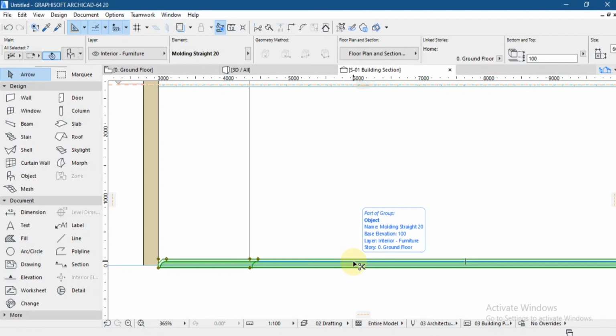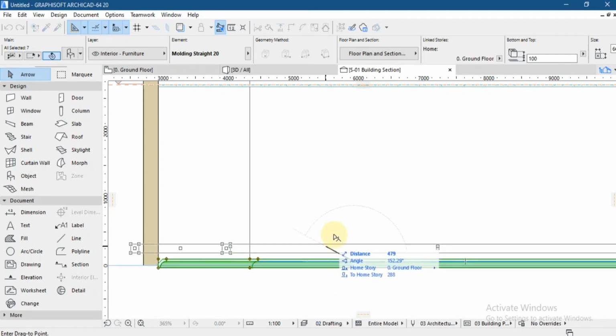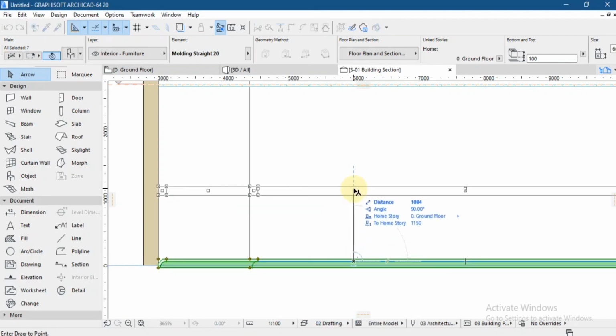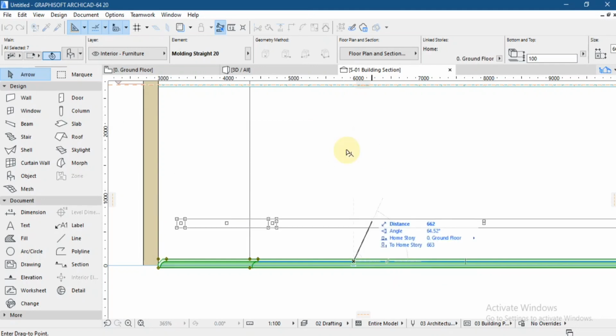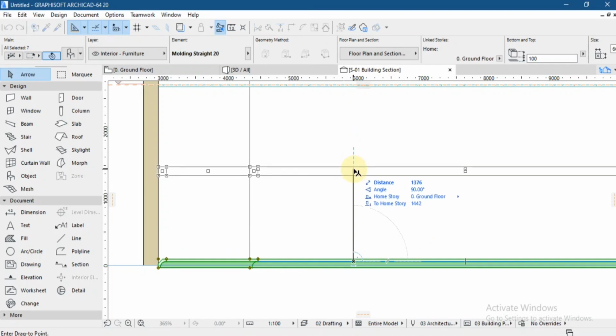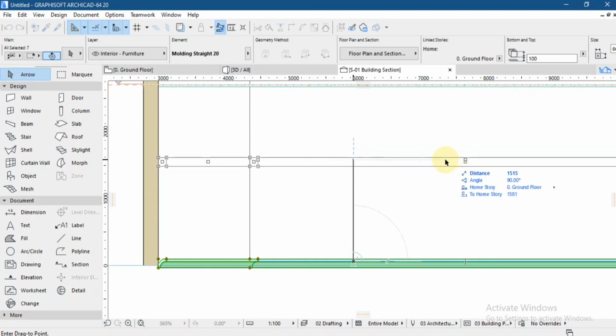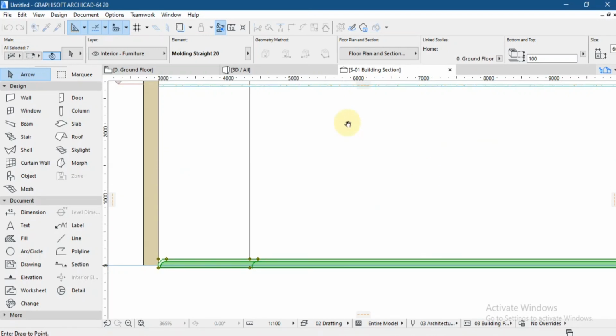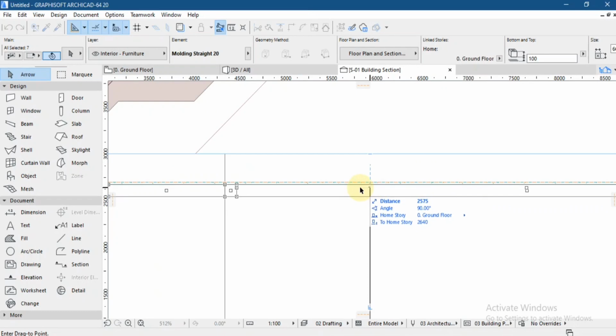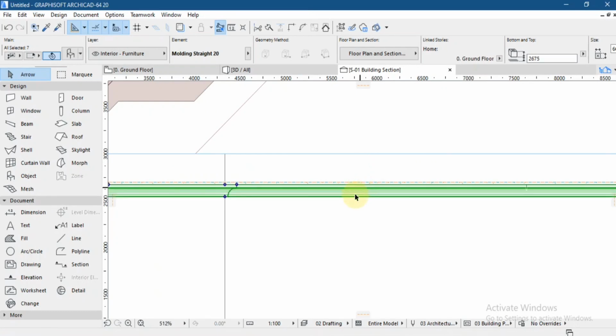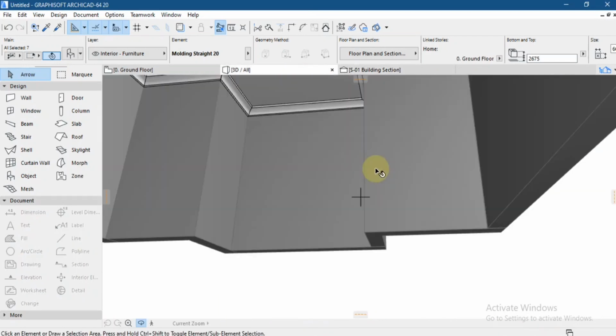Now we drag it, Ctrl D, like I told you before. Drag it in a straight line. If you want to drag it along the y-axis, which is the vertical axis, we're going to hold Shift. It stops you from swerving around. You can either take it up or down, you can't take it side by side. So Shift will help you. Then you take it here like this. Then voila, we've placed it. Now let me show you what we've done.